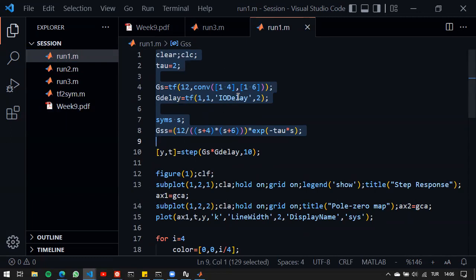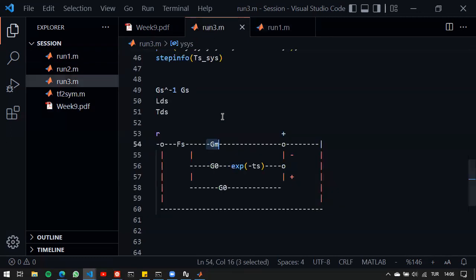We have compared the step responses. Basically, in closed loop, we're trying to achieve that effect. We are trying to get rid of all the delay parts in the denominator. We are just going to design a controller for G0, the non-delay part of the transfer function. And then we will use the structure and we're hopefully going to be happy. So you need this structure and a controller for G0 and nothing else.